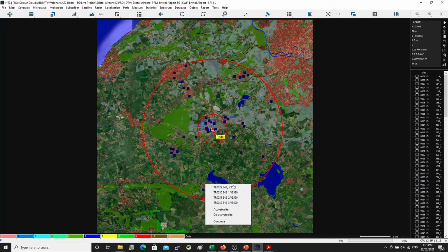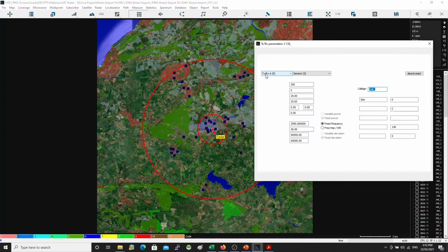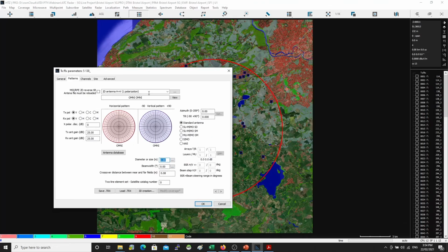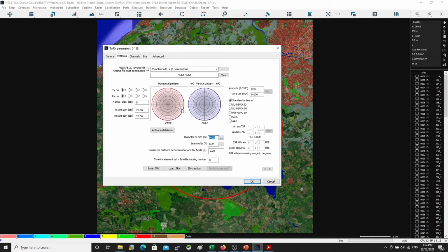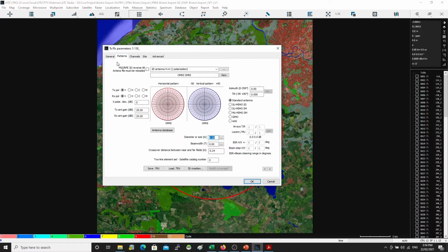You see, I modeled every site as 1, 2, 3, 4 sectors. These 3 sectors are the actual 1, 2, 3. But the first one, this one, is just the benchmark model. I have a benchmark model which is pure Omni, and this is really the most pessimistic case. Although I'm calling this Omni, I'm using directional gain. I'm using the full gain of the smart antenna, 25 dBi.